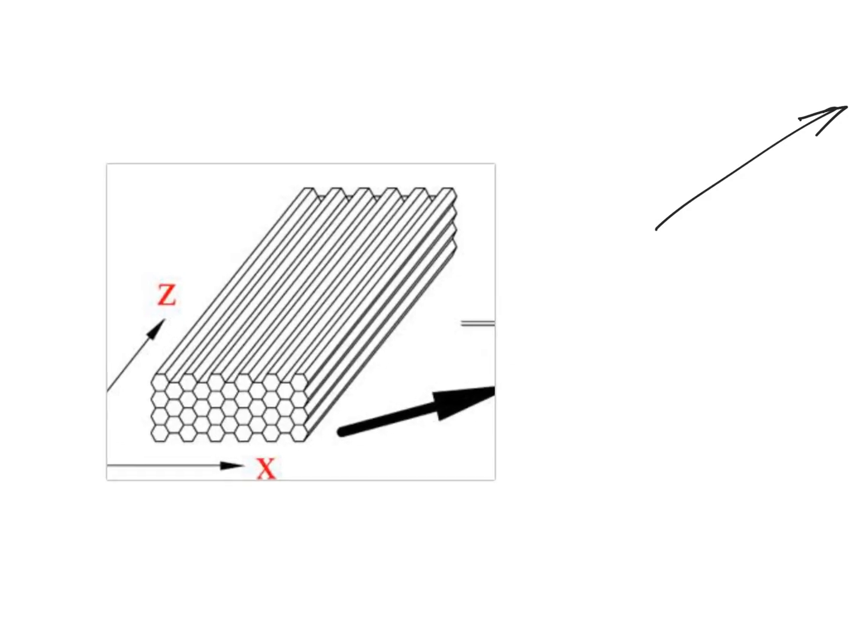So actually you can take a piece of honeycomb if you can get hold of something at some point of time, and you can do that exercise which I described earlier, rotating about three mutually perpendicular axes, and you can yourself appreciate the fact that this particular honeycomb is an orthotropic material. Obviously, from the figure itself, it is clear that the in-plane properties will be different from that of the out-of-plane